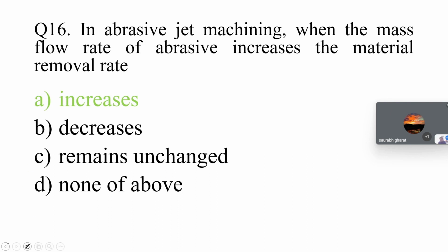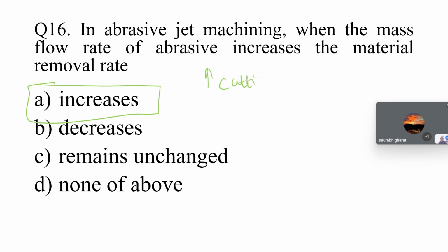Okay, so this increase is your correct answer because you are increasing the abrasive flow rate, which means more abrasive particles will be there for cutting. So your MRR will increase.